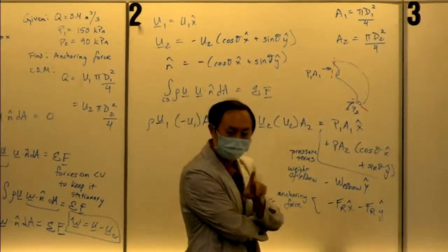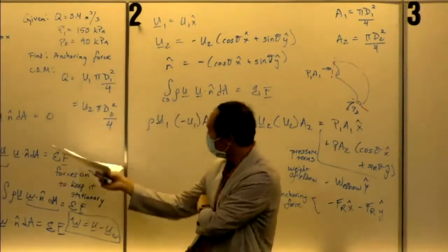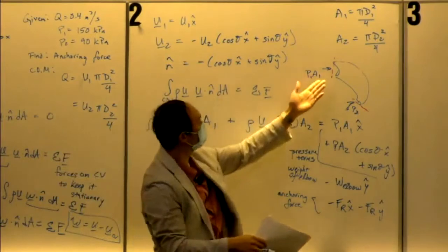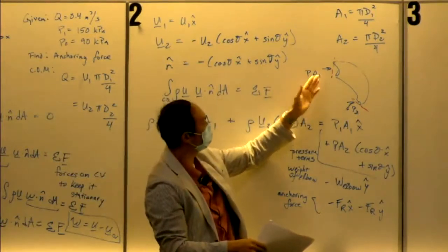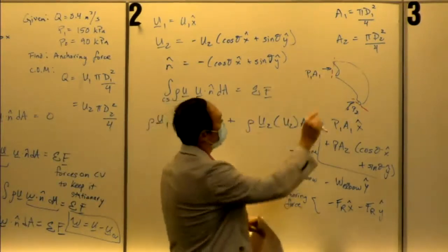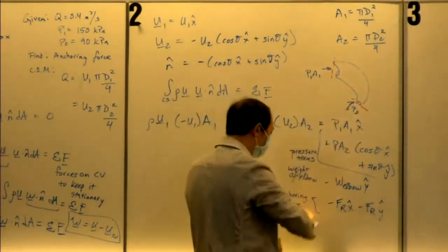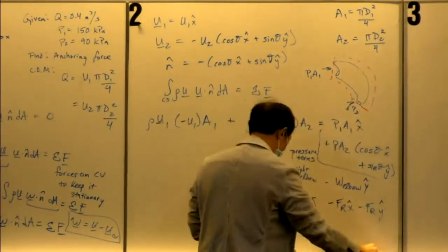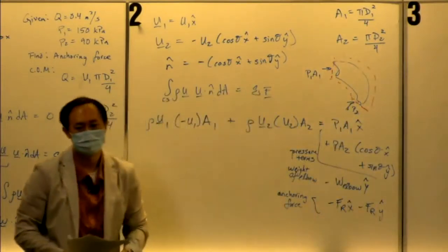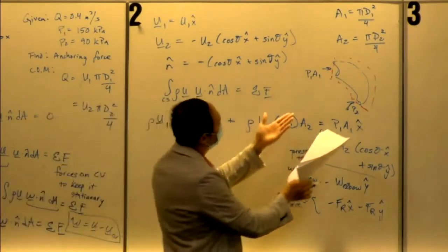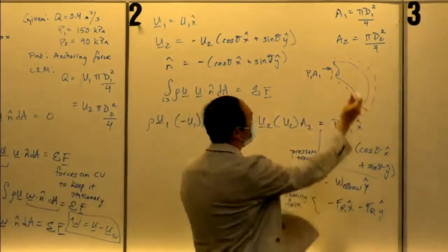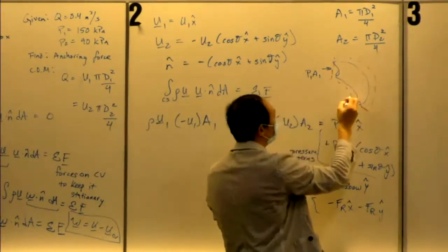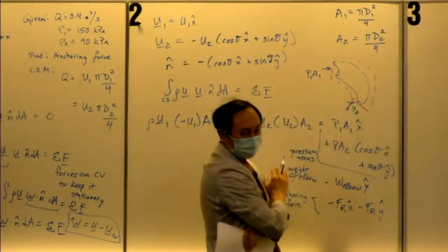So it is very different from the momentum problem. In the momentum problem, we actually cared about the direction of the fluid velocity. But it doesn't matter if you got fluid coming in or out, as long as it's got positive pressure. Basically, your control volume, if it ends there, that is the pressure that's exerted on it. So these forces are with respect to the end direction. So that's what makes it positive. Yeah, because they're only there where the fluid is. Like basically here, this is like a bunch of asbestos or whatever, like pipe fittings. There's no fluid out here. Same with here. They only exist where you've got fluid.